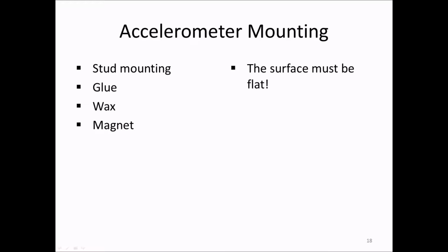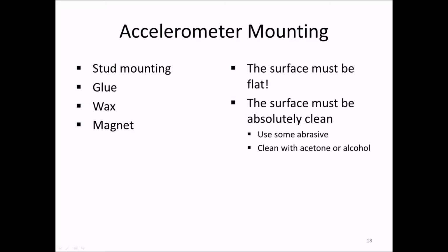Now, common to all mounting methods is that the surface must be flat so that the accelerometer does not rock. The surface must also be absolutely clean. Often you need to use some abrasive and clean the surface carefully.